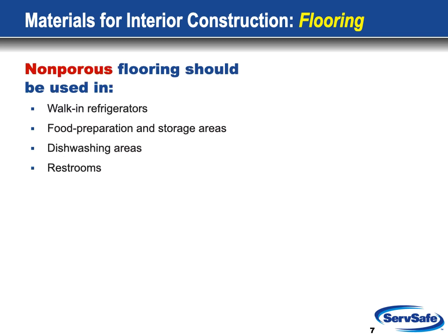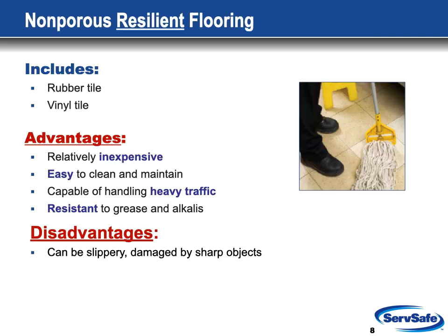It is especially important to have non-porous flooring in areas such as the walk-in refrigerator, food prep areas and storage areas, dishwashing areas, and in the restrooms. One option to consider is non-porous resilient flooring, such as rubber or vinyl tile. These are relatively inexpensive, easy to clean, and can handle the heavy traffic and resist grease. The downside is that they can be slippery and sometimes can be damaged by sharp objects.